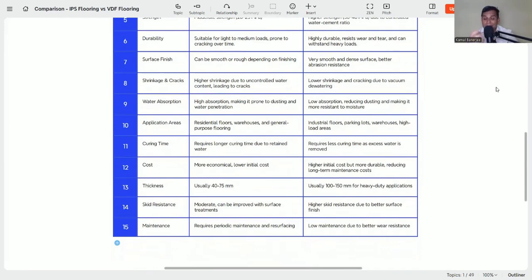If the concrete absorbs more water, what will happen? This water will be a problem for the concrete, because without the water, neither the sulfate ion, chloride ion, nor carbon dioxide can react with the concrete. In the presence of the water, these are all reactive and they make the concrete deteriorate. So that is why the water absorption capacity has to be very minimum.